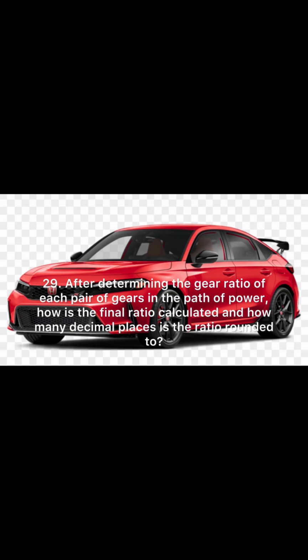9. What is the purpose of the transmission fluid in a transaxle? To lubricate and cool the transmission components. 10. What is a common symptom of low transmission fluid in a transaxle? Slipping or hesitation. 11. What is the recommended interval for changing transmission fluid in a transaxle? Typically every 30,000 to 60,000 miles.